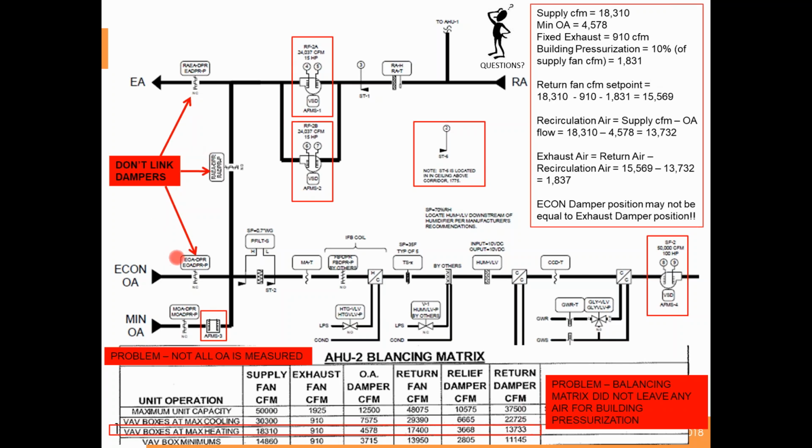If we are not on economizer and we're just in the minimum outside air situation, then this may be closed, but yet we need to relieve a little bit of air through that damper. So you can find yourself getting into trouble in that situation. Again, that's an important thing to look at in the design.